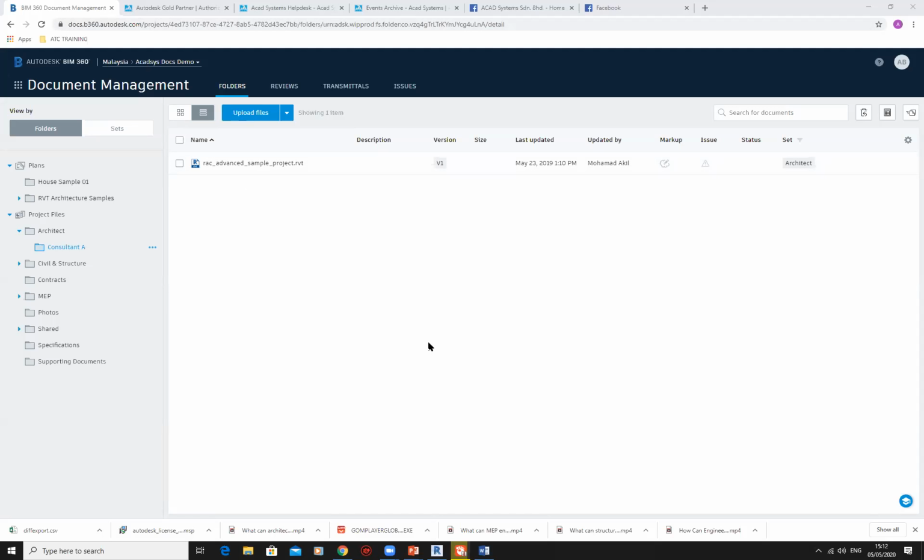If you make the link as an attachment, it will definitely be seen in 2D view in Revit, because whatever you hide in visibility and graphics in Revit will be kept and brought to the document management module. Whatever was last saved in Revit will be seen in BIM360, so you have to be very careful with that.